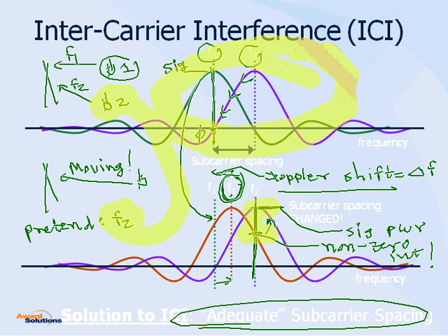So the base station looks at the entire 10 or 20 megahertz signal, and then it will pick the subcarriers by using 15 kilohertz spacing. Okay, so in that case, we cannot do the full compensation.